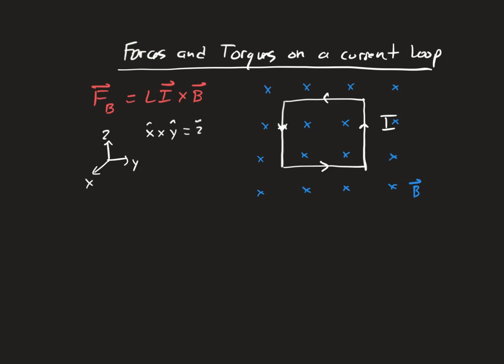That's the same pattern as we have with the force equation up there, which is I cross B equals F. So all we have to do is put a little XYZ coordinate system everywhere that there is an I, B, and an F, with the X and the Y in the direction of the current and the magnetic field, and the force will be in the direction of the Z direction. It's another way of doing the cross product, but it's really a trick for doing it in these circumstances where you can't see my right hand.